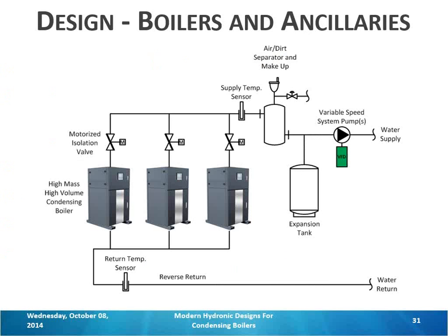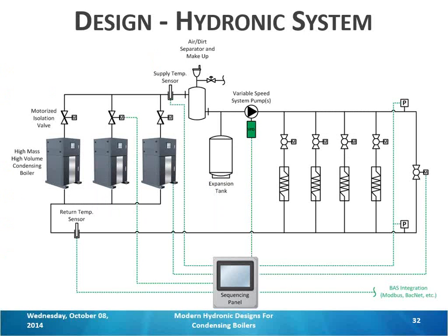But if you think to that Q equals m c_p delta T equation, is delta P in that equation at all? No. So what is delta P telling us? It's telling us the valve position. But if you have a zone that's a gymnasium and another zone that's an office, and they have pretty similar pressure drops, you're not really going to get an accurate representation of what's going on in that system.